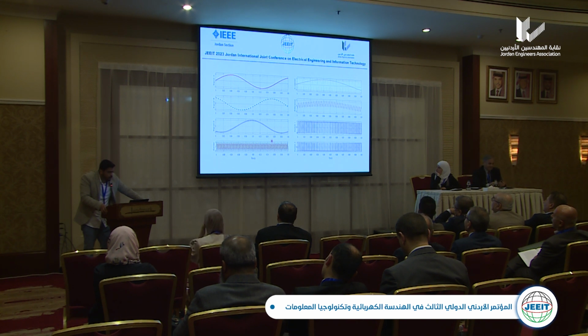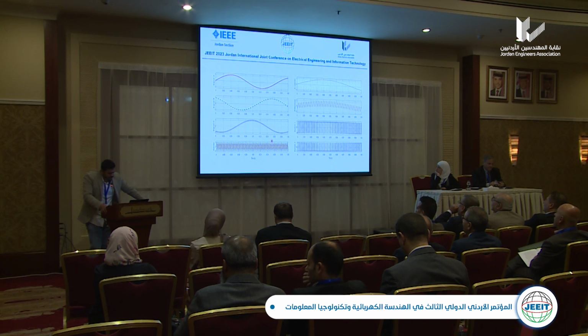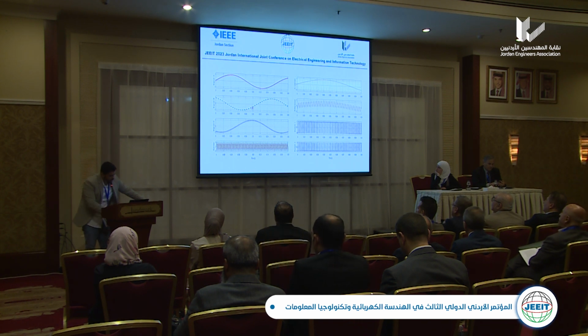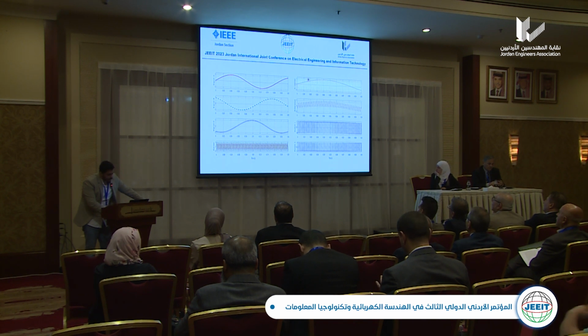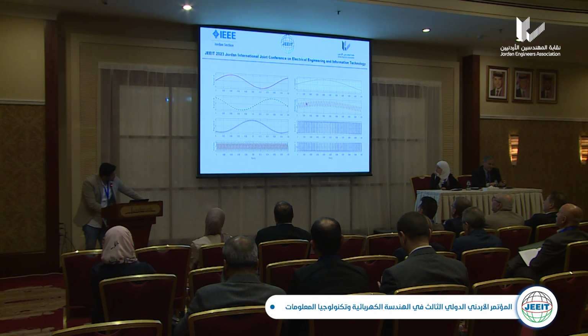Now we will go to the design of a three-phase PWM, pulse width modulation, that we use in order to control the three-phase inverter with 6 IGBTs. We have three reference signals, signal A, signal B, and signal C, and we have a carrier signal. If we take the first signal, signal A, and put it together with the carrier signal, the difference between these two signals will be this diagram, and this is the diagram for switch 1 and switch 4 switching.